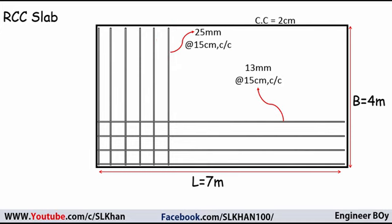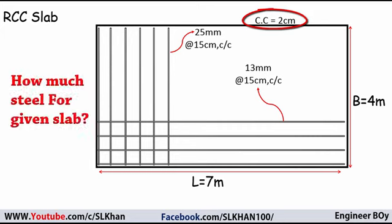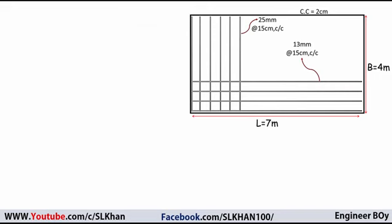If you look at the temperature bars, these are also known as distribution bars. Those are 13 mm at the rate of 15 centimeter center to center, and there is a 2 centimeter concrete cover at each side. So what if we are asked to determine the steel quantity for the given slab? In this video, we're going to answer how much steel is needed for the given slab. So without wasting time, let me go ahead to the solution.